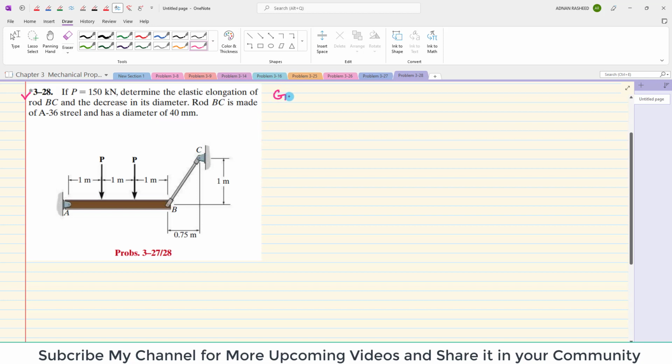So we will start from the given data. It is given that P is equal to 150 kilonewton. And rod BC is made up of A36 steel. This is rod BC. Also, the original diameter of this rod BC, D_BC, is equal to 40 millimeter.